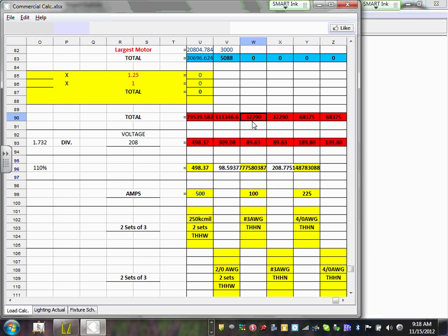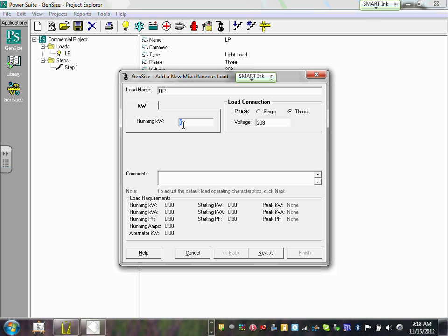Remember, it has to be in kVA. So it's going to be 32.29. Okay? So go there. 32.29. Everybody's okay with this? Now, am I single phase or 3-phase? They are receptacles, so they're single phase. But the panel itself is what? 3-phase. So leave it 3-phase. That's the most confusing part. The panel's 3-phase, and the load is going to be balanced between the 3 phases. Can I have thumbs up, Chad? We got it, gentlemen?